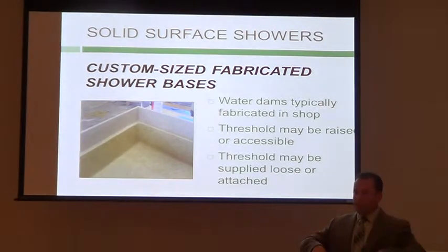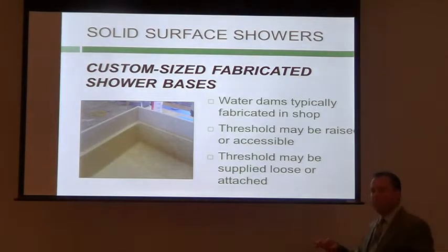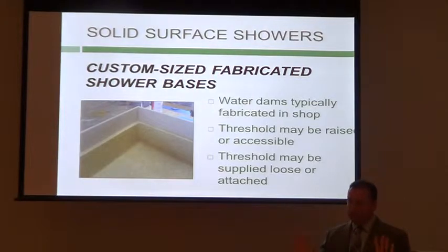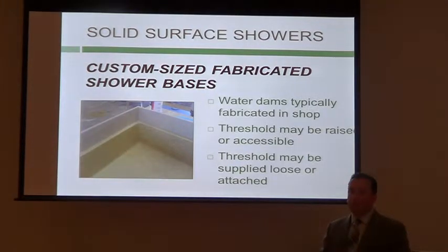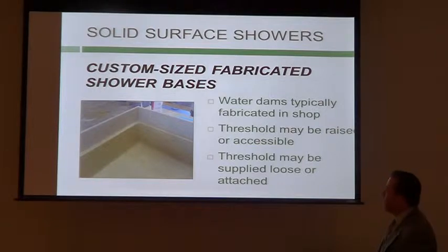Because of the slope to the drain, there's what we call smiles around the perimeter of the shower base. So when the panel goes in down to the floor, either A, we're going to have a little gap in the middle of that panel, on the floor area, that has to be caught. Or I have to scribe the bottom of the panel, which just takes a little more time in the field. It can be done, it can look great, it just takes a little more time in the field, which adds cost. And what do you refer to that top part versus the threshold?